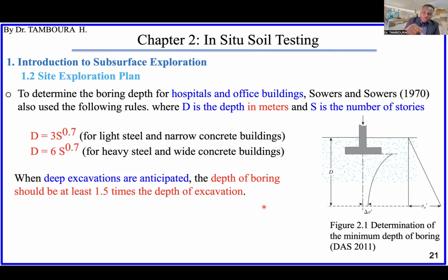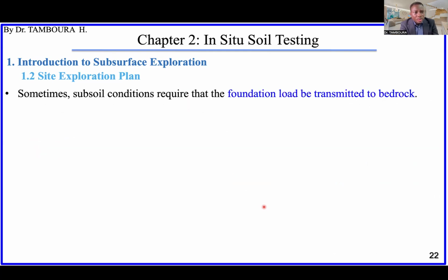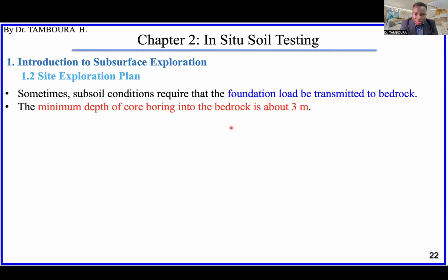Okay, you should go down lower than the level of the excavation. Sometimes the subsoil condition requires that the foundation load be transmitted to the bedrock, so you have to reach the bedrock. In that case, as I said before and I repeat here again, you have to core bore into the bedrock about 3 meters. Okay.